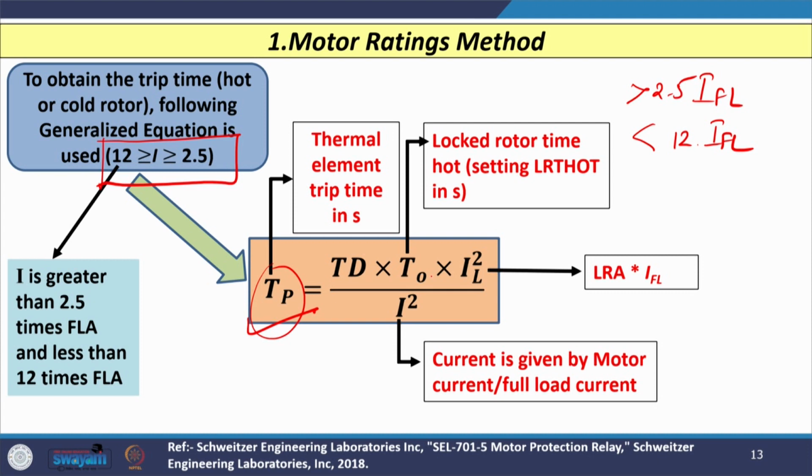T0 is the locked rotor time when the motor is in hot condition, and we have already discussed that the LRT hot time is normally given. In the earlier example, it was given as 15 seconds, so we can consider that here.